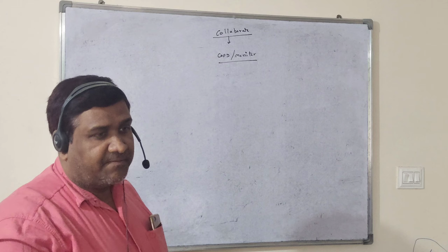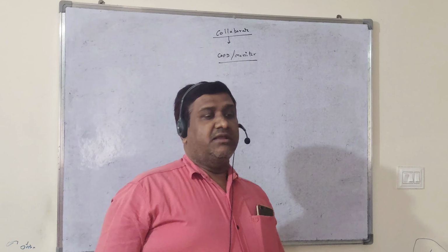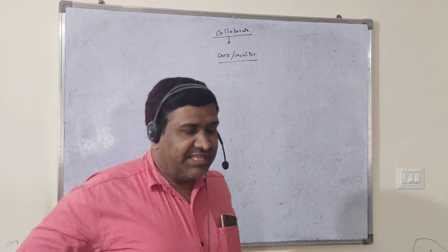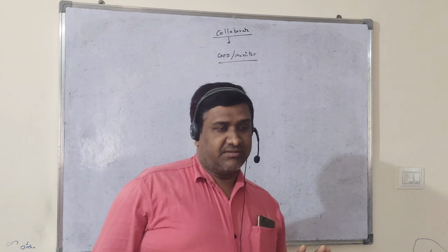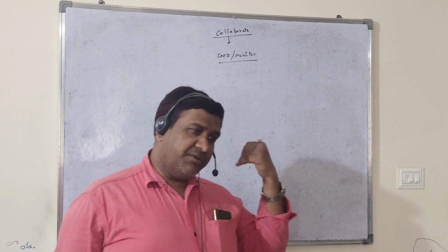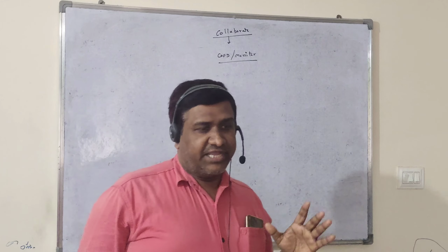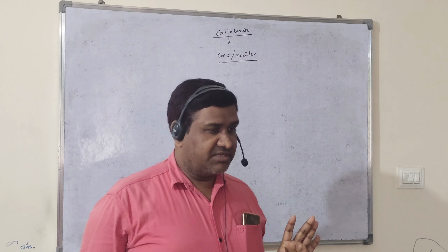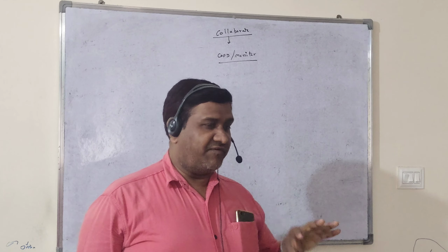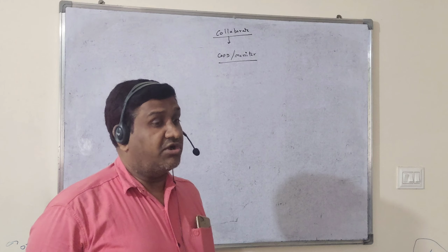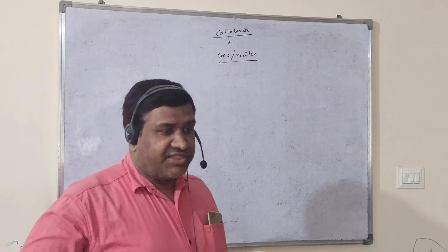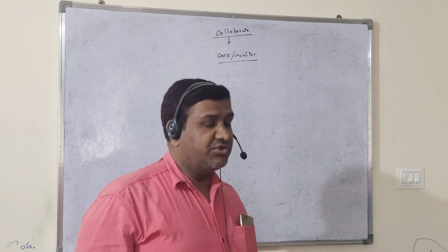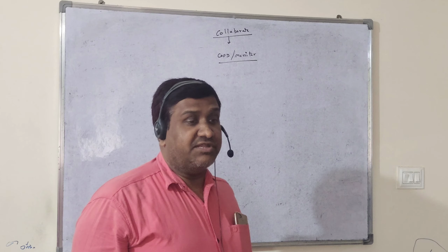It's very important because when you work in AutoCAD, each and every component we can copy from one file to another file. It's possible in AutoCAD as well as in any other tool or application, because we can go with Ctrl+C, Ctrl+V, copy paste. We can copy from one file to another file. But in Revit, that is not possible. We can't do it, but some of the components they have given in such a way that only those components we can copy paste. The rest of the components will not come.